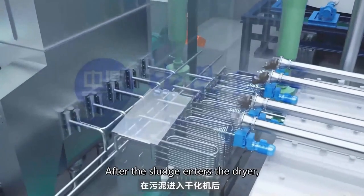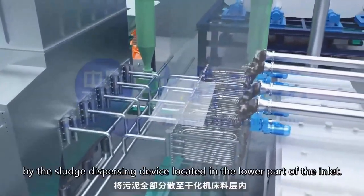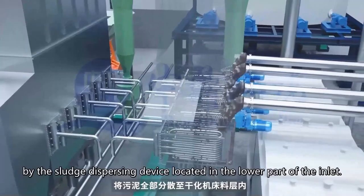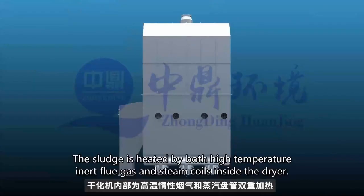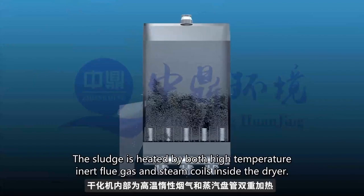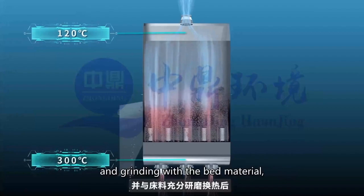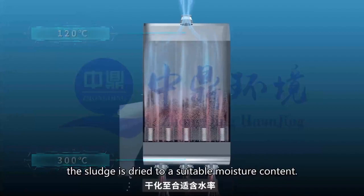After the sludge enters the drying machine, the sludge dispersing device at the lower part of the inlet disperses the sludge into the bed layer of the drying machine. Inside the drying machine, the sludge is heated by high-temperature inert flue gas and steam coils. The sludge undergoes heat exchange with flue gas by convection, and after thorough grinding heat exchange with the bed material, it dries to the appropriate moisture content.